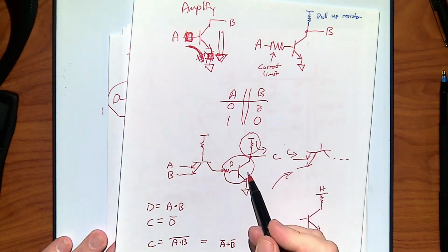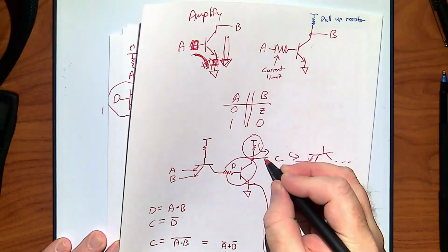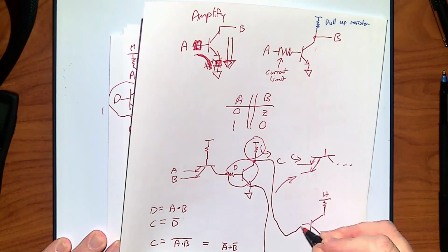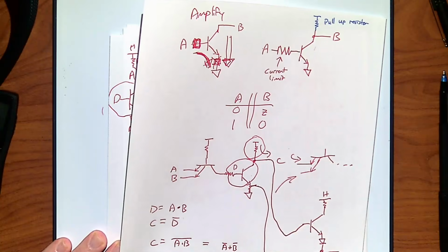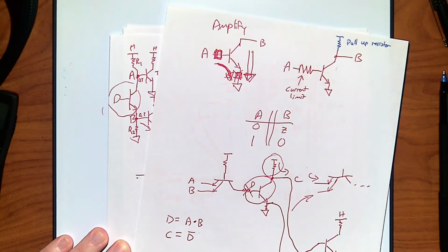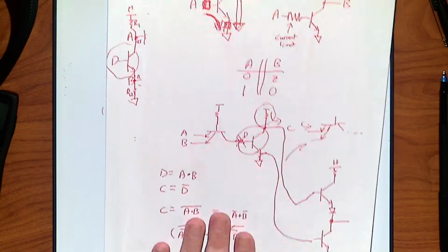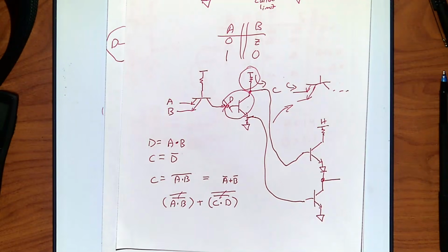We just make that one this. So all we do is we hook two out, and this one goes down here, and this one goes there. We put a resistor here to complete that configuration, which means I don't need one there. And that right there, if you look up, is your first cut of a TTL NAND gate. That's the one everybody gets. It's that one right there.